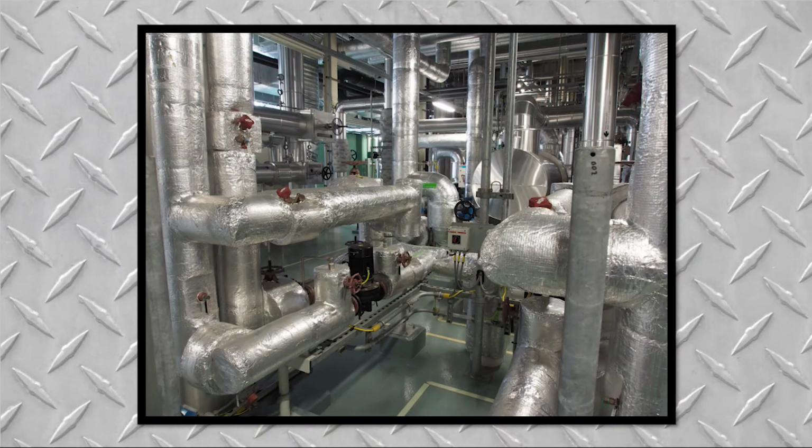It's also important to note that uninsulated chilled water pipes can cause condensation to form from the air in the room. Now, if the chilled water temperature is below the dew point of the air, and for chilled water, it's going to be in the 40s Fahrenheit, you would expect there to be condensation if you don't insulate. But here's something that's not obvious. If any of the condensation seeps into an existing insulation, it makes it worse than no insulation at all. Wet insulation causes the piping to act as if it were bigger, losing more energy and causing the water temperature to increase. You'll also have the problem of mold forming and possibly rust on steel pipes.